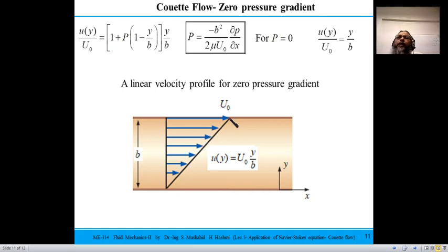So you would have a typical velocity profile, and obviously where your pressure gradient term, or your p term, is 0, it is only because b cannot be 0, u cannot be 0, mu cannot be 0, only thing that is 0 is dP by dx. Then you have a straight line profile. If p has different values, you would have a different velocity profile.